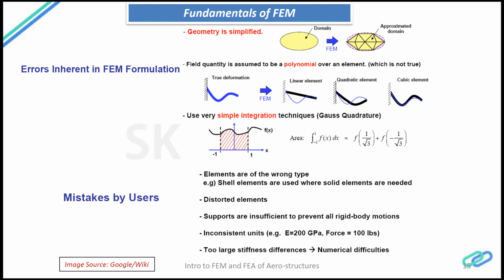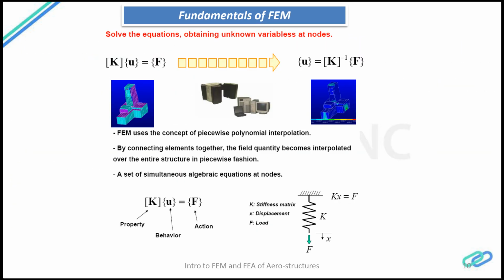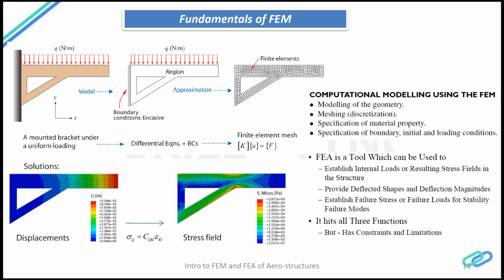Sometimes during post processing of the finite element, when we extract the results, there will be options for using averaging, elemental averaging or nodal averaging, and that can make a very huge difference. So one has to really keep these things in mind.